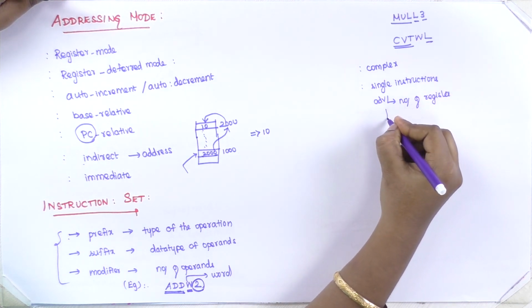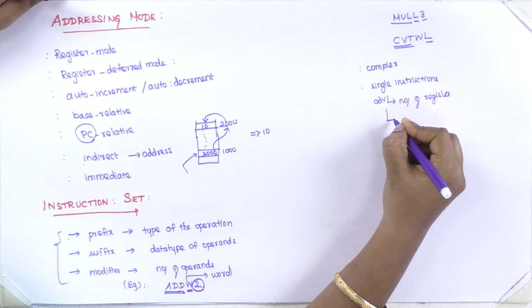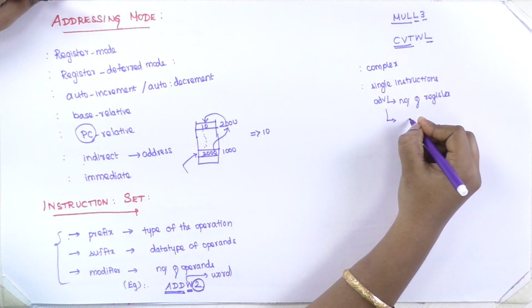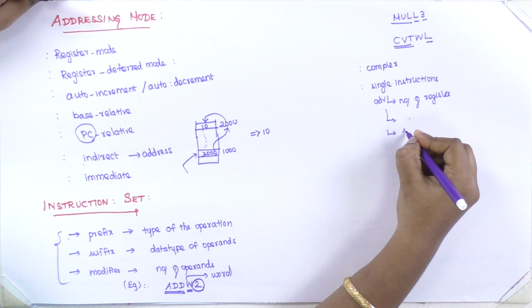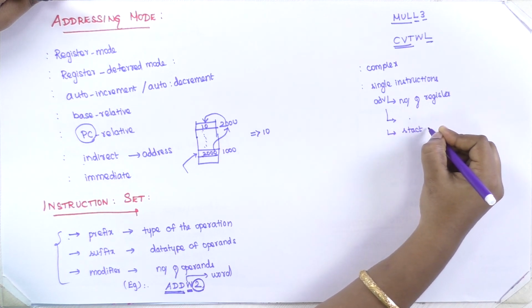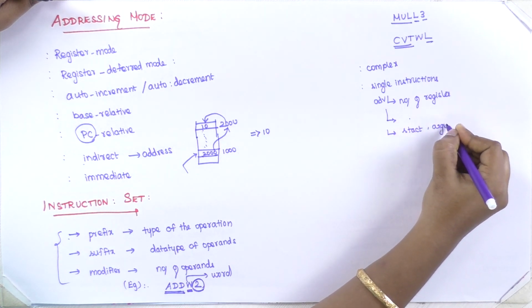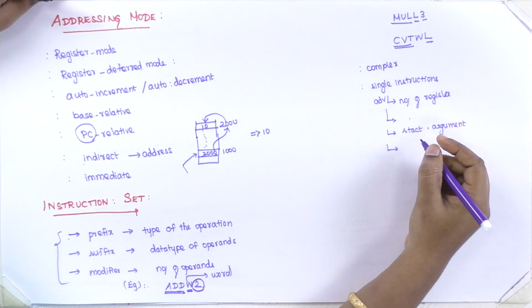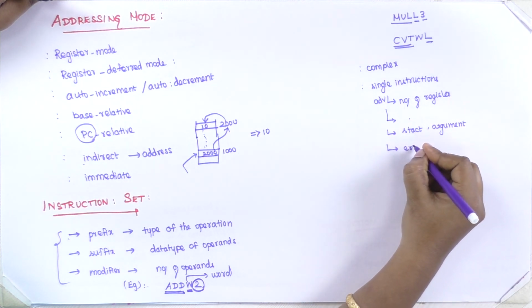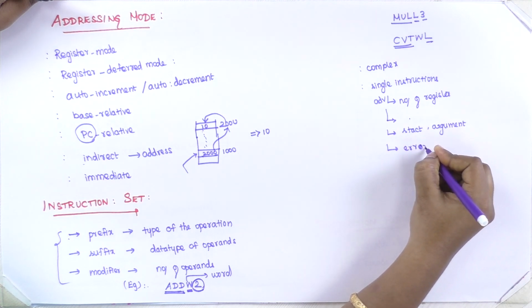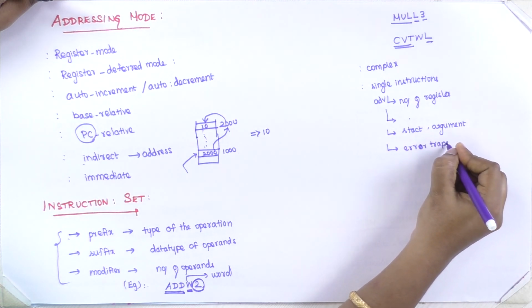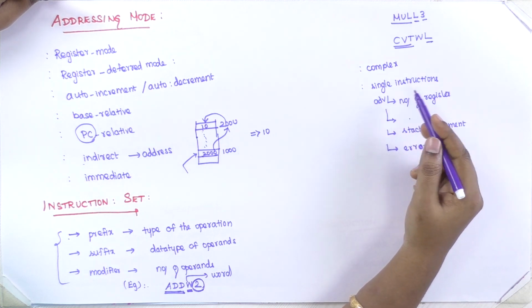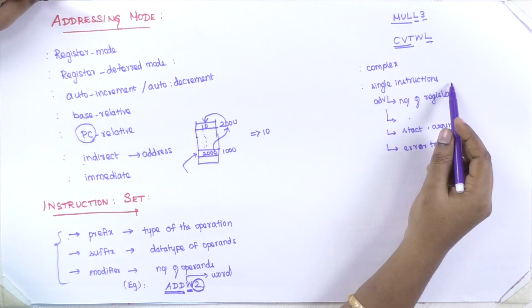It passes a list of arguments to a procedure. It maintains the stack frame and argument pointer. Then it also sets a mask to enable error traps for arithmetic operations. So these are the advantages of implementing the frequently occurring code as single instructions.